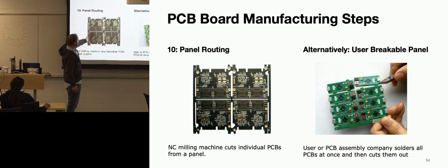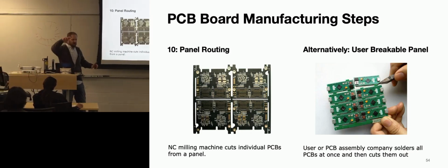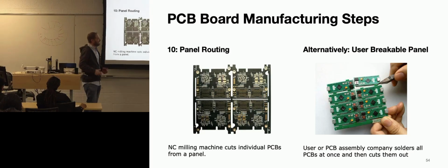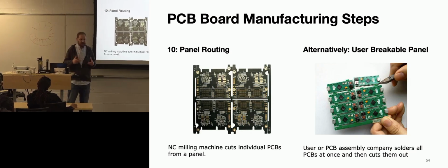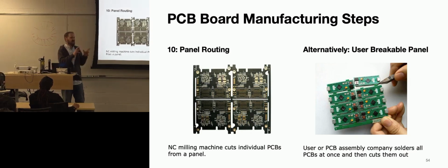What they're going to do is they're not going to make an individual PCB. Typically, they're going to panelize it. So their equipment is set up to take PCBs probably about this big, 2 feet maybe by 1.5 feet. And the big manufacturers, like PCBWay and JLC PCB, they have a set of requirements. They say you can have PCBs that are this size, and they have to have this